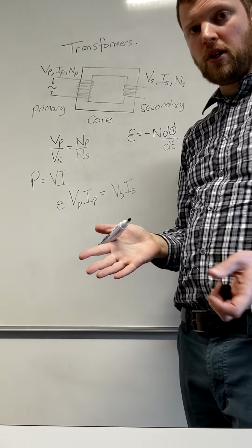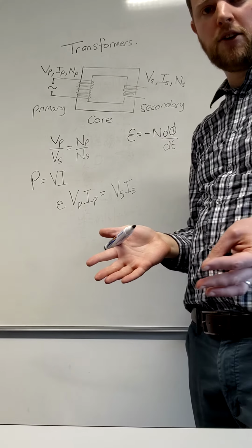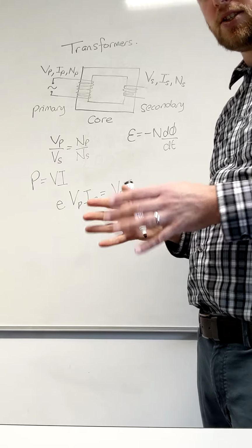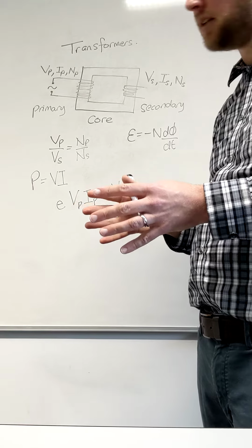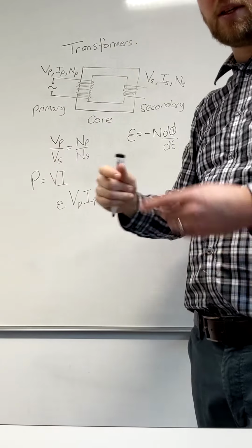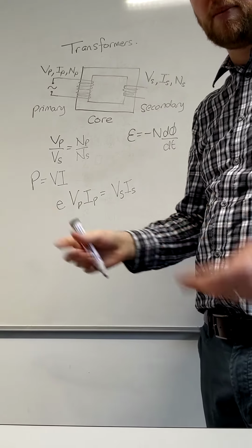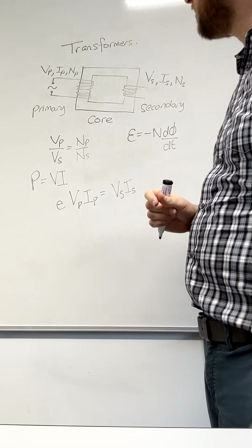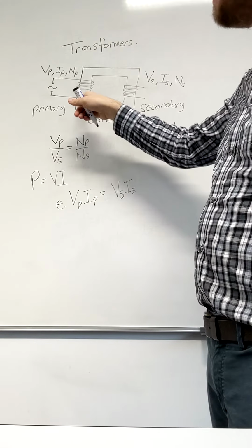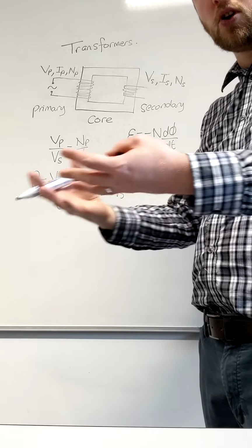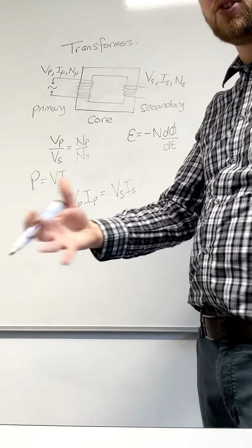If you ever go near an electricity substation, you can usually hear a buzzing. And that buzzing is the transformer vibrating at a particular frequency. Because these are magnetic, they will attract and repel other metal materials that are around them, which will cause them to vibrate backwards and forwards. So because they're vibrating and making a sound, those are sources of energy loss: sound energy, kinetic energy.